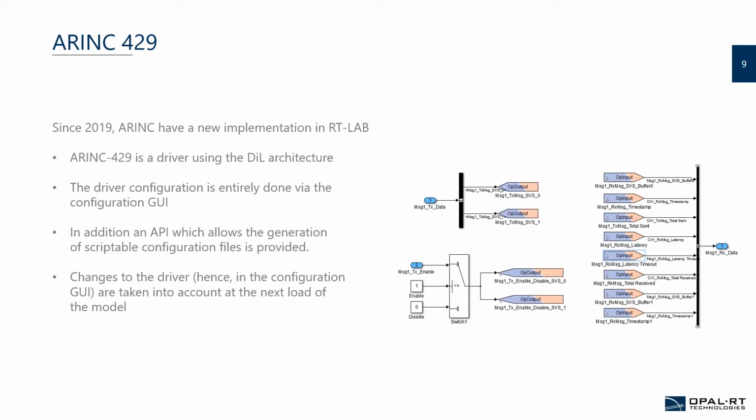Since 2019, we have migrated more and more of the architecture to the DL architecture, which takes some configuration externally of the model, because we don't change them on the fly and real-time performance is not needed. We put this configuration into the RT Lab environment, externally of the Simulink model. That lightens the model size as well, and makes it more comprehensible.